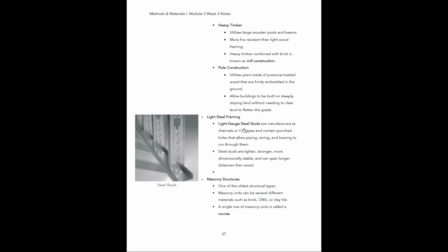Over time the wood flooring has expanded and contracted, and that movement of the structure has actually pulled the fasteners loose. When you step on it, you're actually hearing the nail rubbing in and out of where it was originally. Okay. So the thing about steel is it's more stable. If you were to subject it to temperature changes, it's going to take a lot more than wood to distort its dimensions.